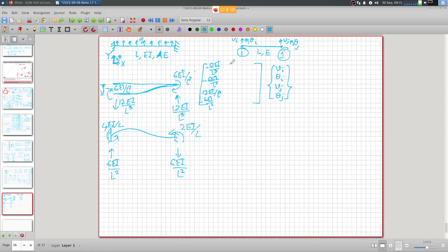So you have 6EI by L square, 4EI by L, 6EI by L square, and 2EI by L. Right?